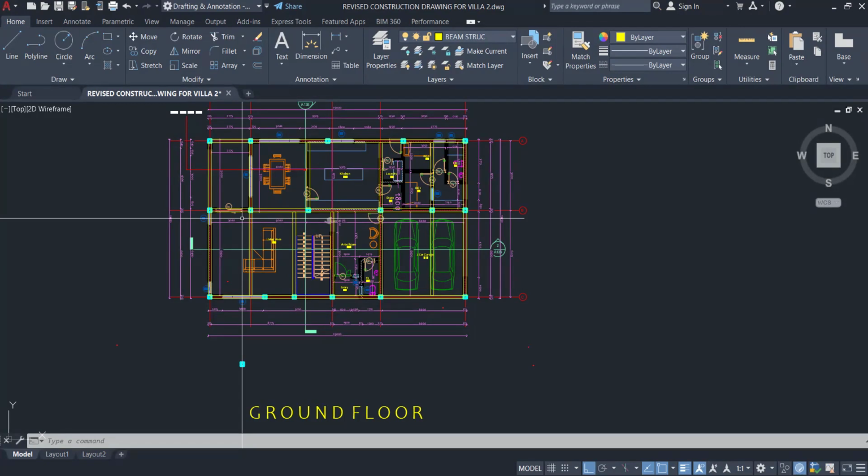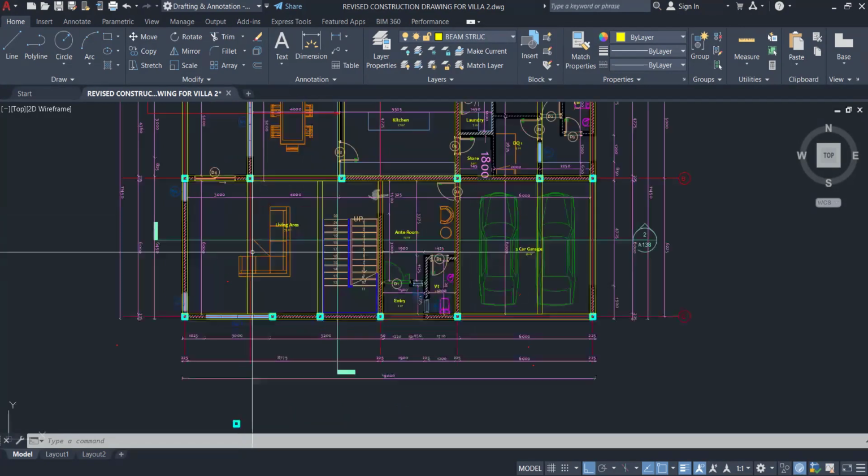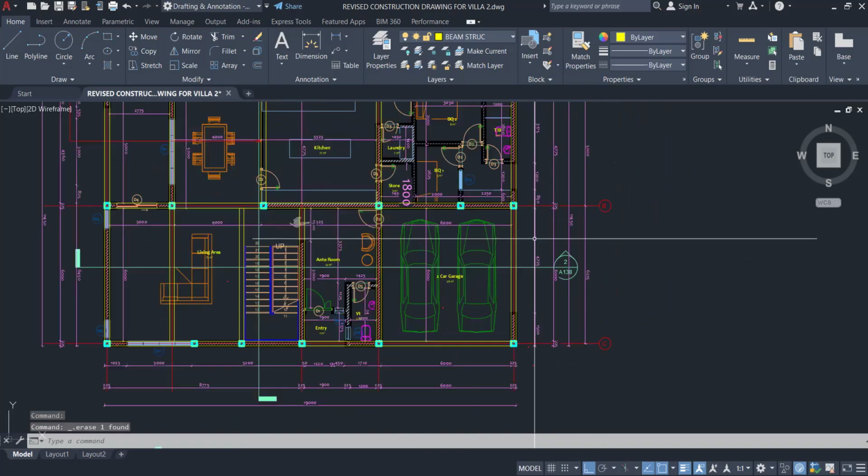It's just going to chop material. Like for example, this living room now, or this garage, if I decide to remove this beam completely, you see that that area is wide, 6 meter by 6 meter, along the X, along the Y, 6 meters. But if I design it like this, 150 mm will not pass in terms of thickness of the slab. If your client can pay, no problem, you can do it.